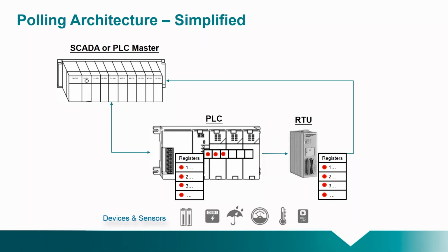Once you go beyond one PLC, they are connected via a bus, and these protocols all work with a set loop rate or poll rate. And the master device communicates to each device in loop, let's say once every second, and reads the registers on that device and then moves it to the next PLC or RTU. This is a well-known and proven architecture, and thanks to advances with Ethernet speeds, the amount of I/O and polling rates continue to increase here.